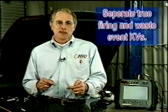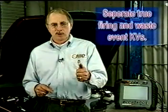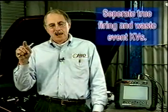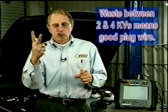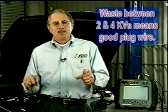Now, for diagnostic purposes, it's going to be important for you technicians to always separate the kV demand for the true firing event that happens on a compression stroke and analyze the waste firing kV values, as you will see, because if you have an open in any of the plug wires, the waste firing kV value, if it is between 2 and 4 kV, that tells you electrically the plug wires are sound, and of course the terminal connections.